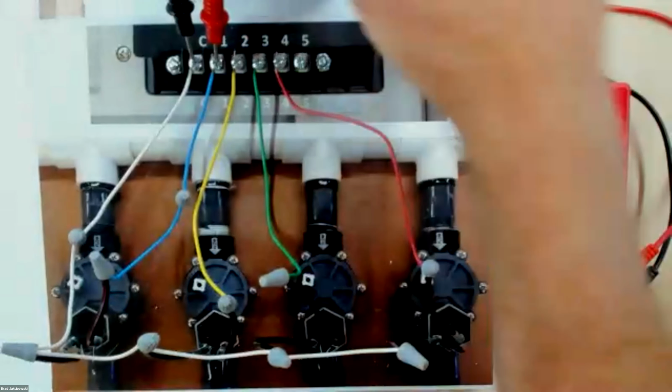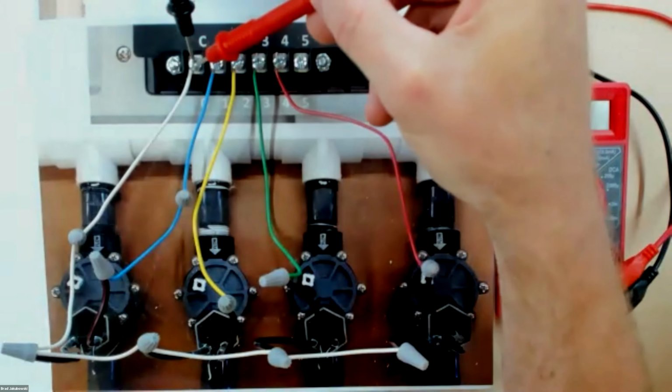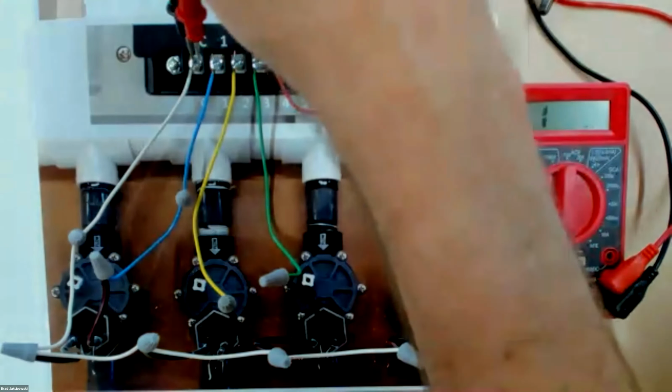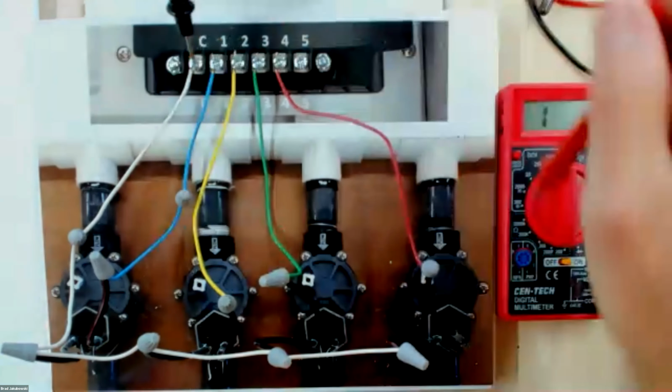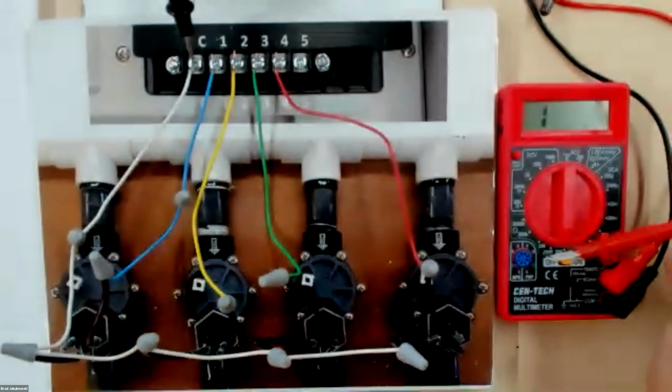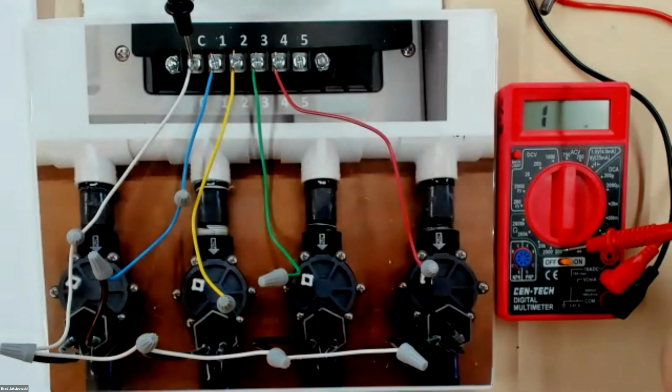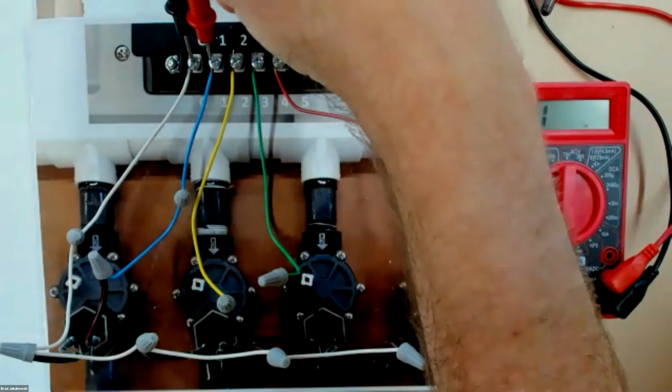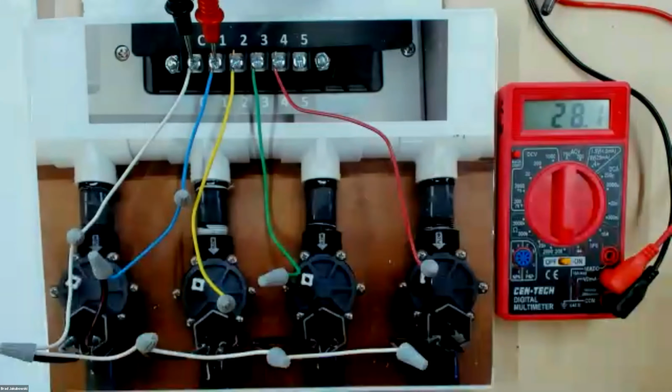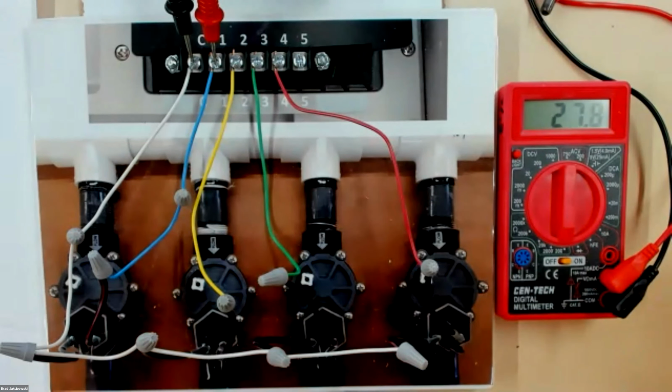With this first one here, go ahead and put the black lead on the common right there. Once you've got your multimeter set to 200 ohms, that's the range we're going to be dealing with, we can see what our valve is reading. Essentially, solenoid number 1 is giving us 27.7 ohms. Good, bad, or indifferent? Is that within range? You bet. So number one looks good.